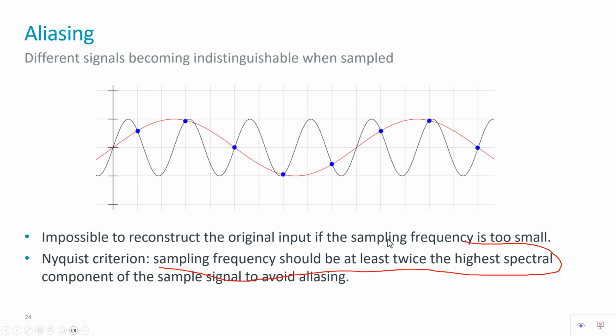Any discrete signal has a space, has a time, has an intensity, as well as has jaggies, and finally has high frequency information that appears as low frequency information. So if I'd like to reconstruct my signal when I convert it to the frequency domain and send it, I need to make sure that I did the sampling with twice the maximum frequency present in the signal. So the continuous time signal can be completely recovered from its samples if and only if the sampling rate is greater than twice the maximum frequency present in the signal.